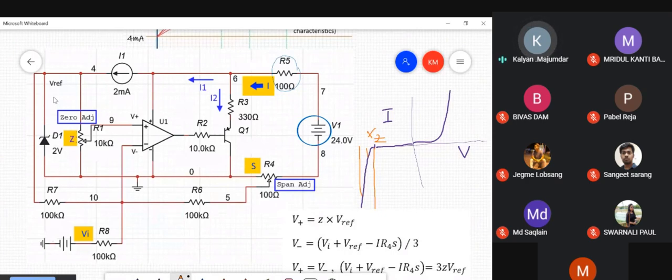We want to avoid this, and that's specifically the reason why instead of using a resistance, you're using a constant current source. That means you're driving this Zener diode with a constant current, which means you're operating at a fixed value of I, and hence you get a fixed voltage across this device. So the use of a constant current source instead of a resistance ensures that this V reference is constant irrespective of input supply changes. It also is compensated for temperature changes, that is implemented in a different way. So the ultimate objective is to get a constant voltage at this point, V reference. So we have achieved that.